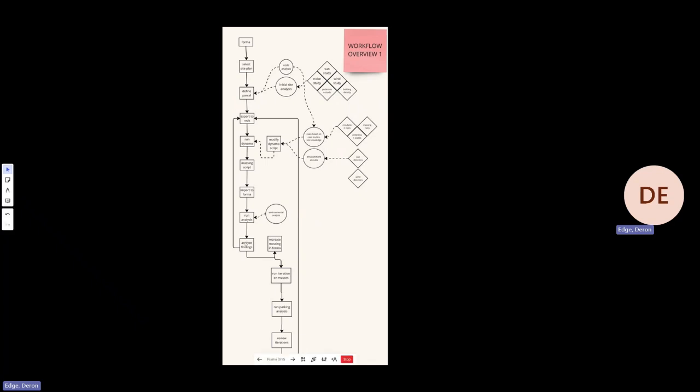At which point, if there's modifications, and typically there will be, since we're going to iterate through this process, we'll go back up to the export out to Revit and then run the script and go back through this process again, putting in different inputs. As we work our way through the process, we'll eventually get to a point where the massing is good with where we're at. At this point, we want to go into TestFit, and TestFit will start implementing some of the additional interior layouts and options there. It also gives us analysis on pro forma, more detailed parking counts and things like that.